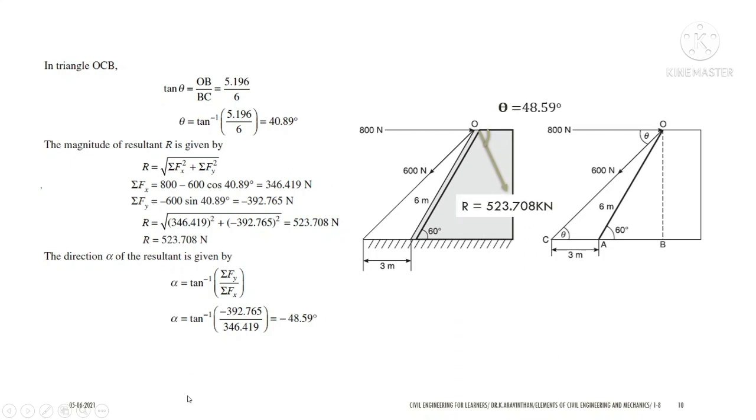So you got the resultant in terms of negative. What it resembles is that you have taken angle with respect to the horizontal axis as 40 degree, and if the angle is negative, you can take it with respect to the opposite side. So this is the opposite side, which is 48.59 degree. So now the resultant is acting in this opposite direction of the force.